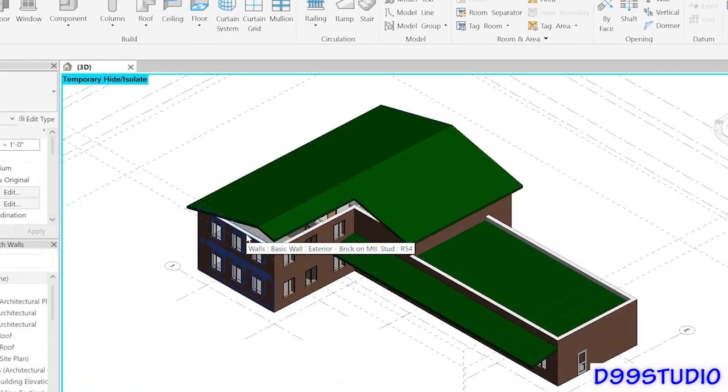Okay, highlight the exterior wall. Press tab. Don't click yet. We're getting the same chain. Move your mouse very slightly to the inside face of the wall, and it should highlight the inner chain instead. So you can see it there highlighted. I'm going to go back to the outside face. There's the outer chain. Here's the, I lost it. There's the inner chain right there.